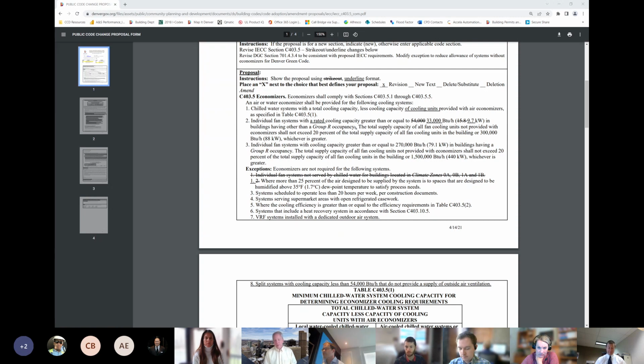However, what's happened with the expansion of these systems into low ambient conditions, which is a good thing. This is one of the things we're happy with, low ambient air source heat pumps. But the problem with these VRF systems is that when they're operating as an evaporator with the unit outdoors, they're making a very, very cold refrigerant because they're having to suck heat out of minus 5 degree air. Manufacturers will tell you, you really shouldn't include zones that require cooling at the same time when you need heating in these extreme conditions, or just in our design conditions.